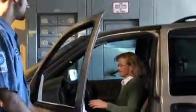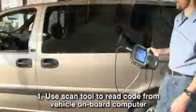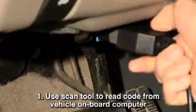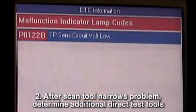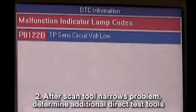At this point, let's do a quick recap. 1. With the check engine light on, the tech is going to use a scan tool to read the code. 2. After he gets the code, he can determine that the problem is within the TPS circuit.